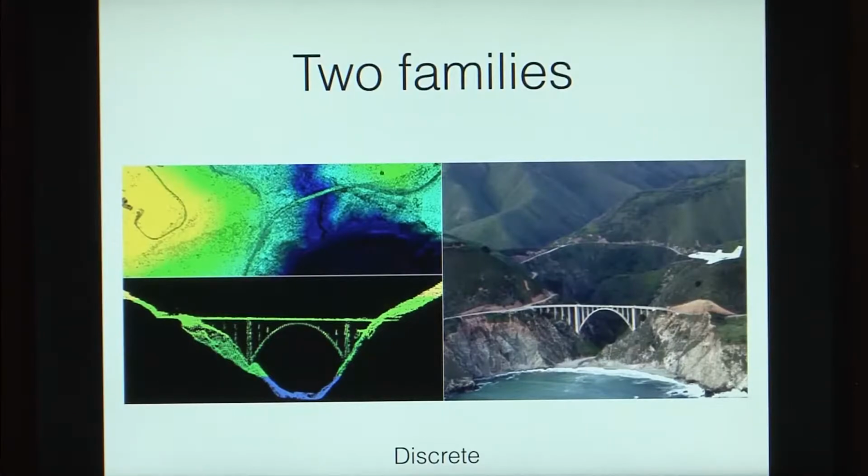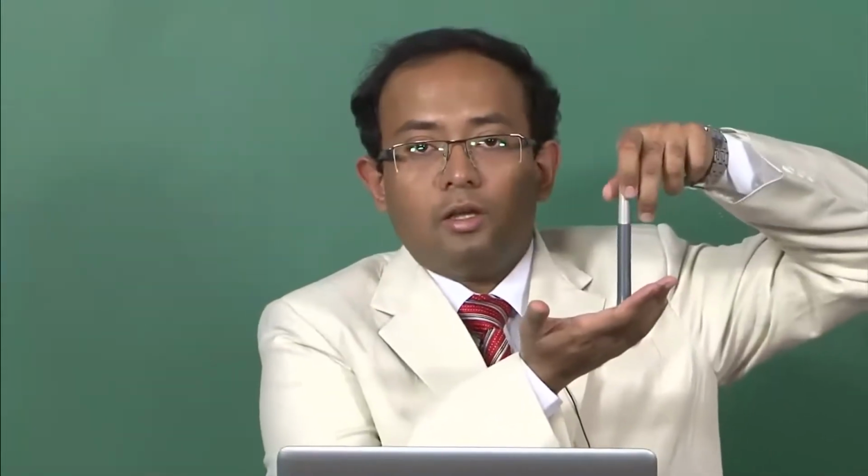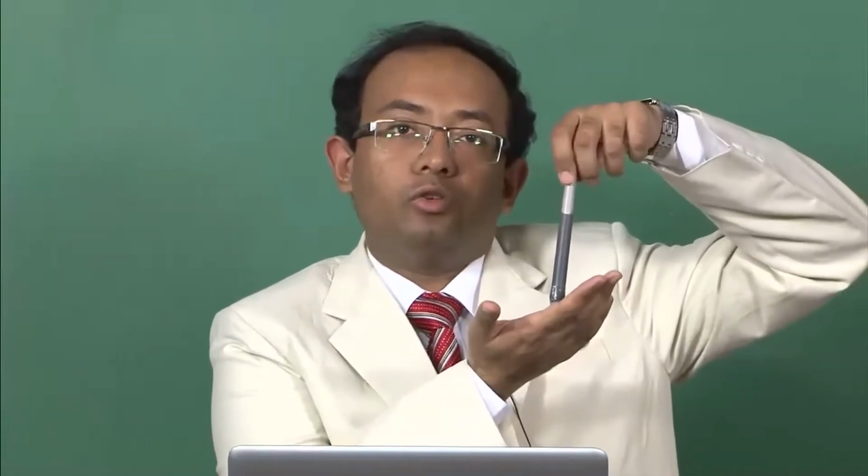Now, what sort of wavelengths do we use in LIDAR? Remember that it is a laser system and a laser beam has a fixed wavelength. So, what are the wavelengths that we use? There are a number of considerations here. One is that your beam should be able to interact with the object. So, essentially we use those wavelengths that can interact with the object. Two is the safety criterion. For instance, if you are putting a laser light on an aircraft and it is shooting down to the earth, if somebody is looking up onto the sky, or if somebody is intercepting that reflected laser beam, then his or her eyes should not get damaged.